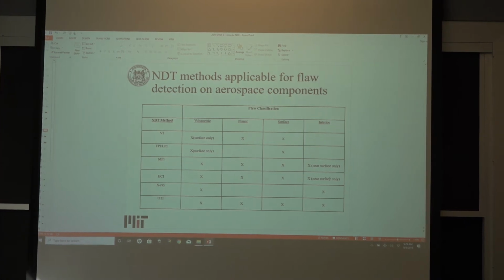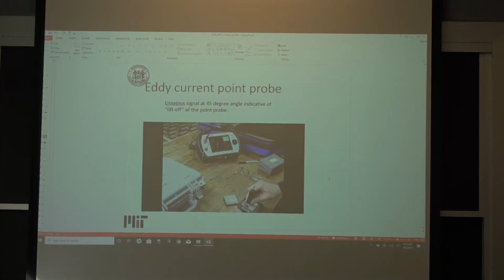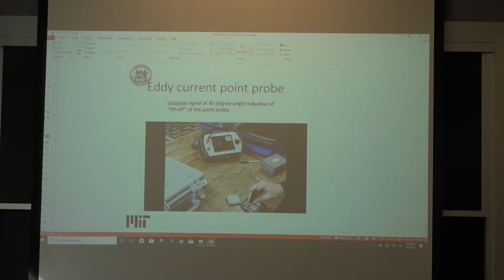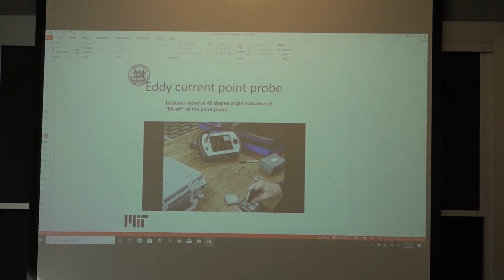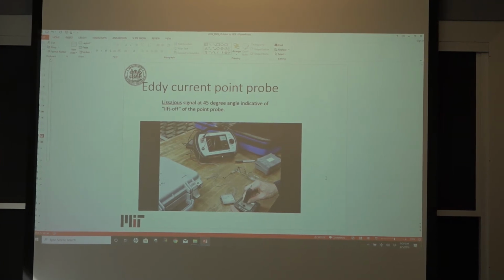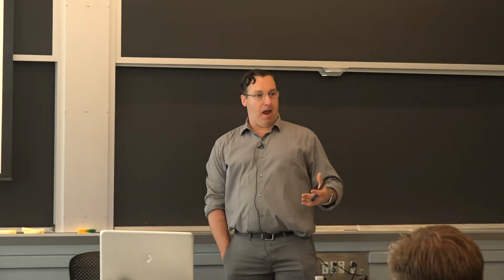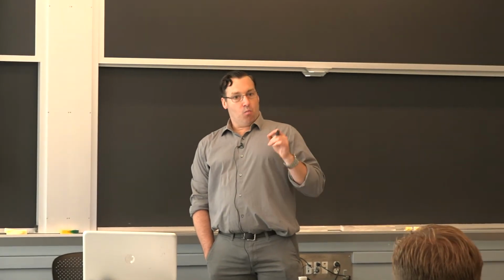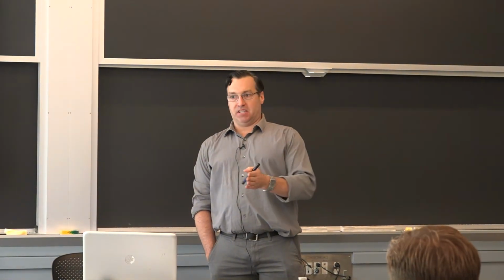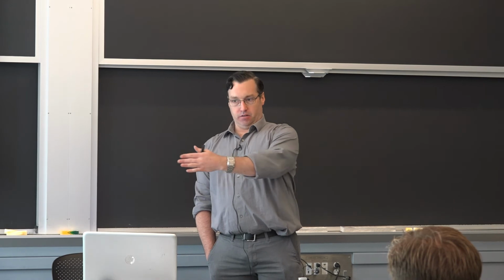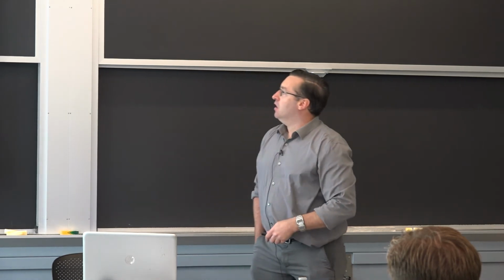So you can have what's referred to as ultrasonically noisy material. If you're working with titanium alloys, aluminum alloys, or things like that that aren't homogeneous, the trace elements used to fabricate the alloy will affect how the ultrasonic waves scatter when you're trying to interrogate the sample.